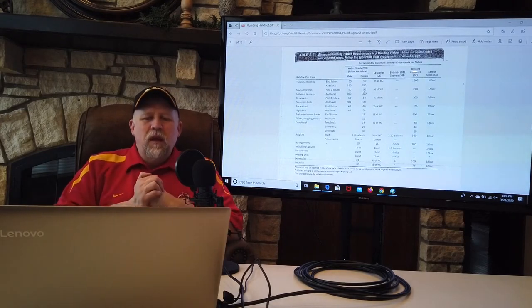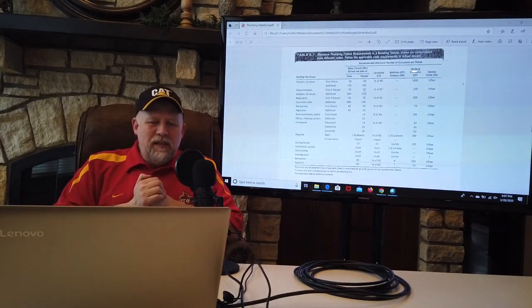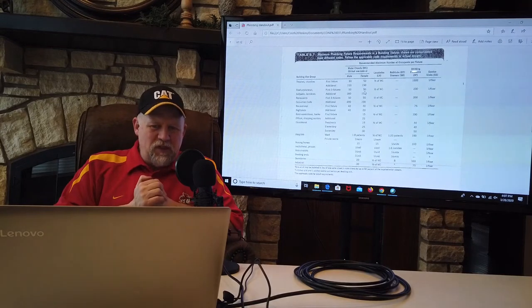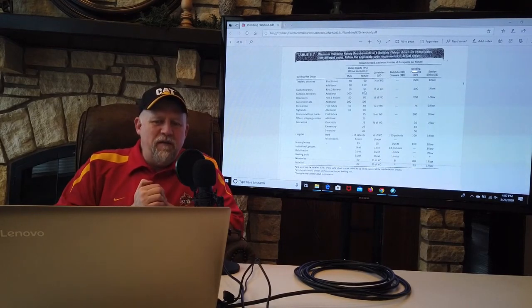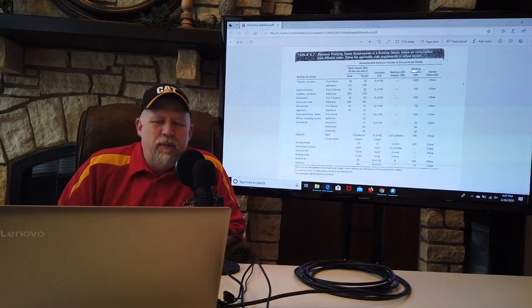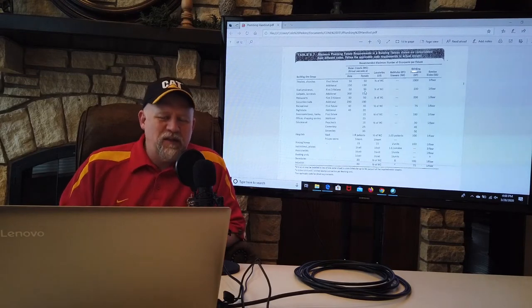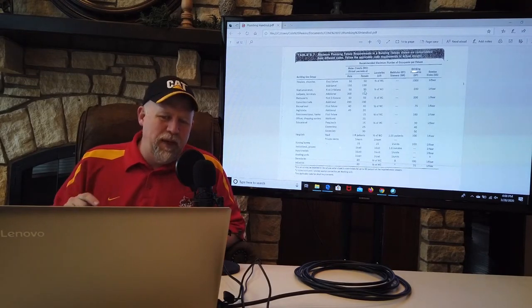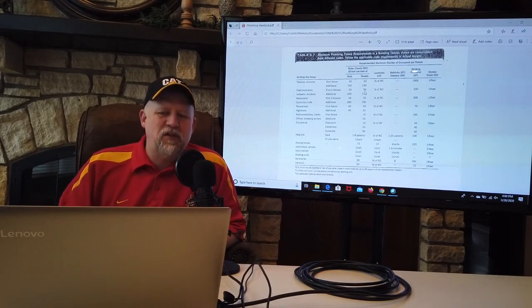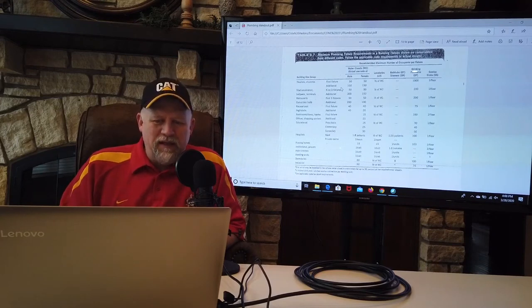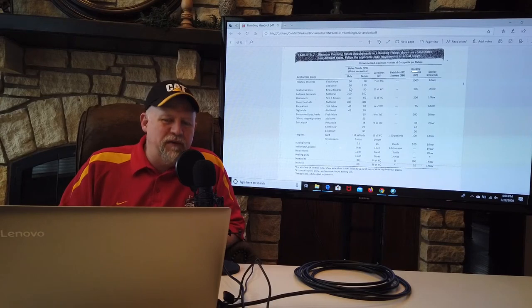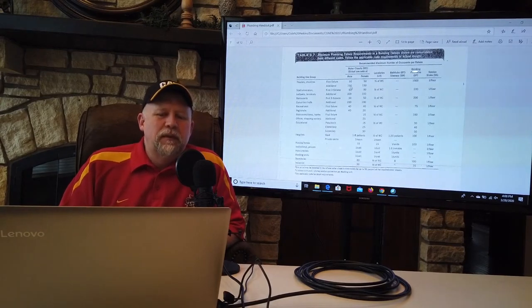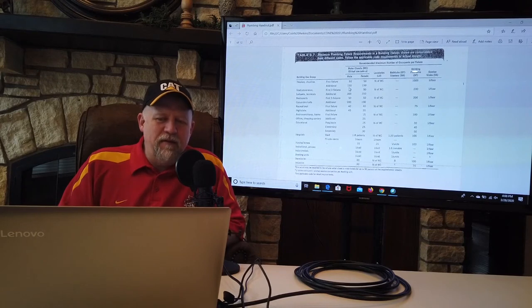Theater or church. What this is saying is for the first fixture, you can have one fixture per 50 people, but only for the first one. As soon as you go to 51 people, you need a second fixture. And then what it's saying is the next additional fixture can handle 150 more people. And then after that, it's 150 everyone after that.